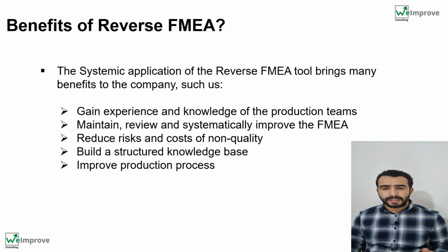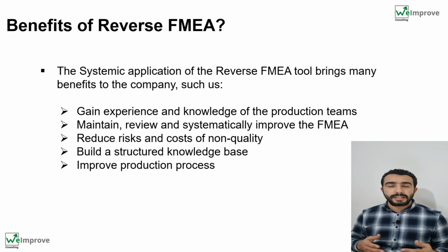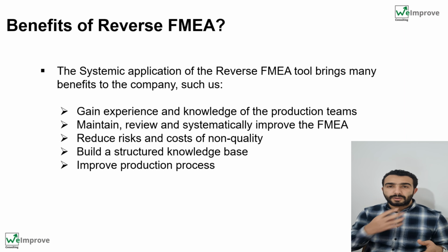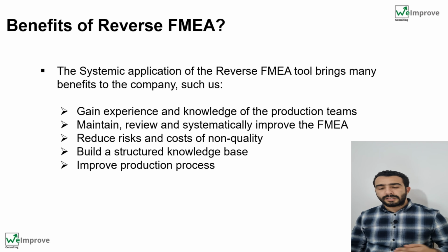Secondly, one of the benefits is to maintain, review systematically and improve the FMEA. As I told you in the beginning, many organizations just implement the FMEA at the beginning of the project and forget to make systematic improvements and updates. So this is an opportunity or benefit of the reverse FMEA that allows you every time to make this update and this review.